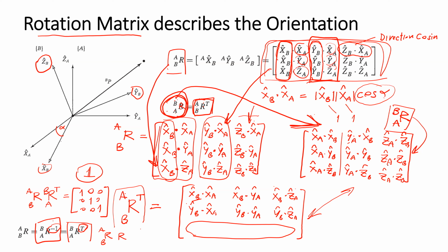In general, we describe the position of the thing in 3D space by 3 degrees of freedom, X, Y, and Z, and we need 3 more degrees of freedom to describe its orientation in 3D space. But why? Now, for the rotation matrix, a 3 by 3 matrix, we need to obtain 9 components of the matrix.